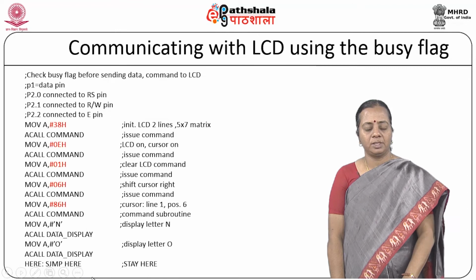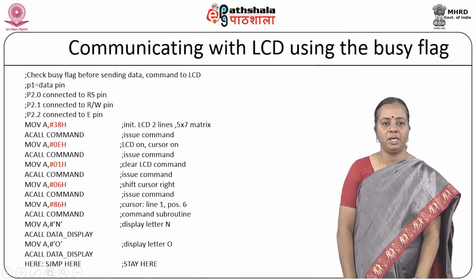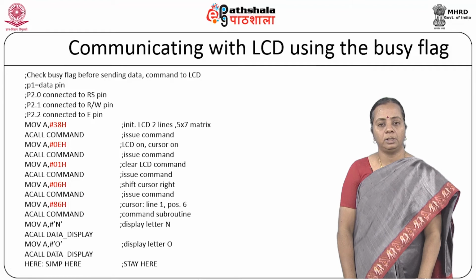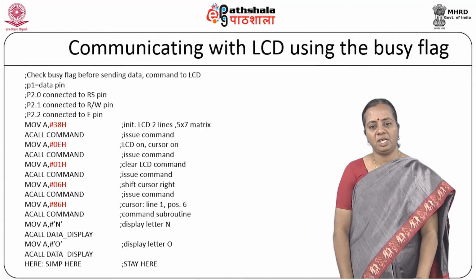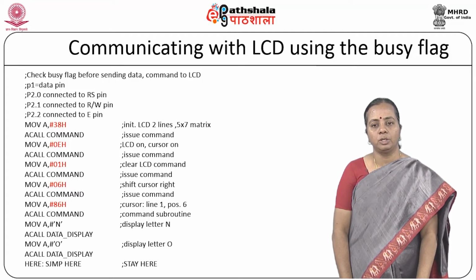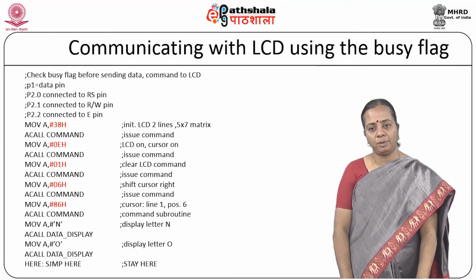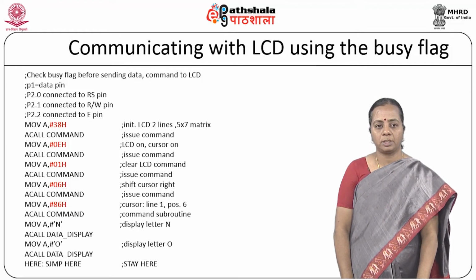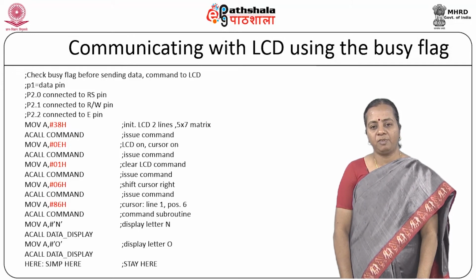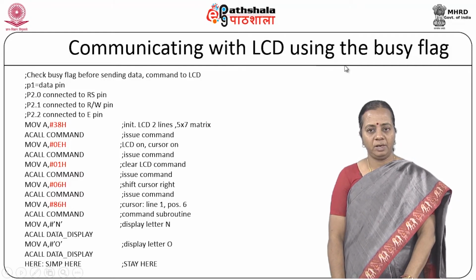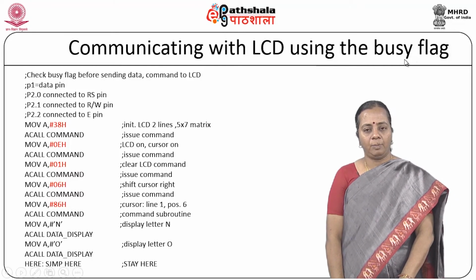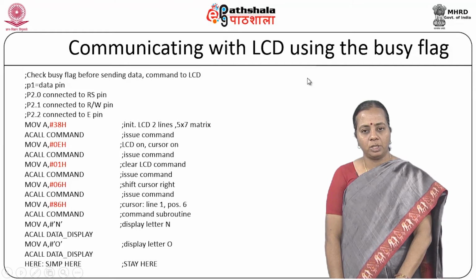So now we will go ahead with something that has been initiated: how we will be interfacing the LCD with the 8051 controller. Sometimes we want to see whether the busy flag is there or not. If the busy flag is there, then it should not be in a position to write. If the busy flag becomes 0, then it has to write. Now I just connected the busy flag with P1.7. So port 1.7 is connected with the busy flag, so that by looking at it, I will be in a position to understand whether I am busy or not. Based on that, I can write it.